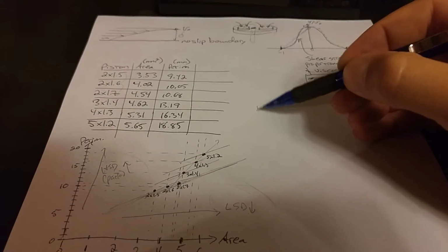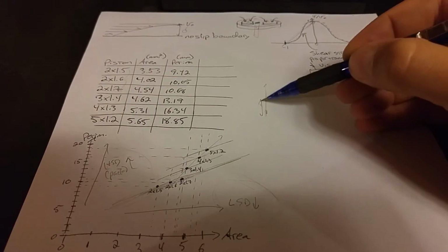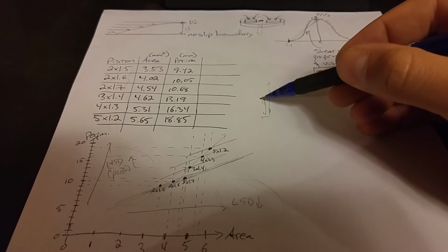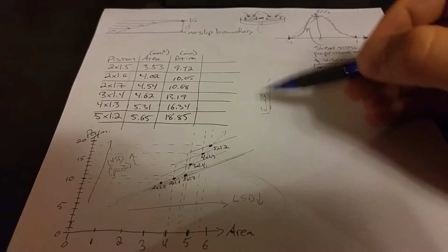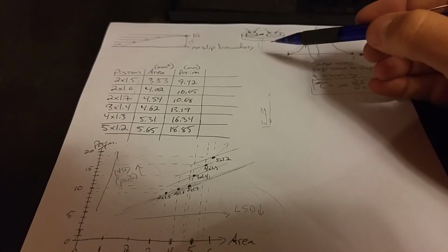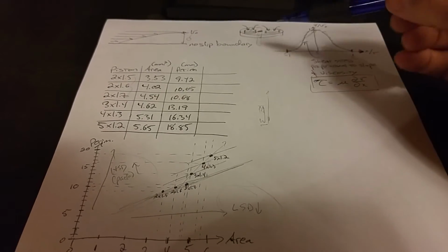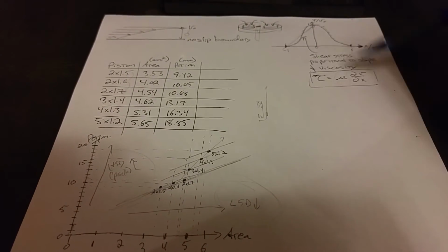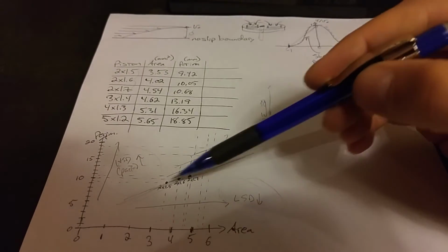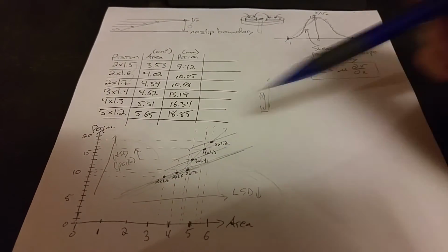That means with less total suspension travel, I have less space to absorb the energy of a landing off of a jump, which means I might want to run thicker shock oil and or use a shock piston that gives me more pack.